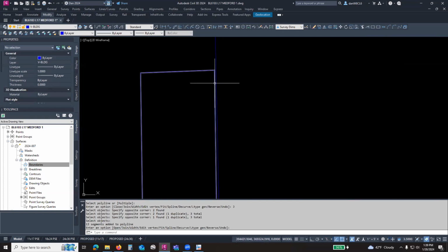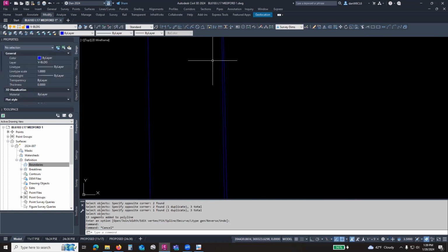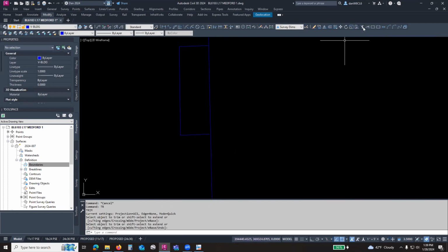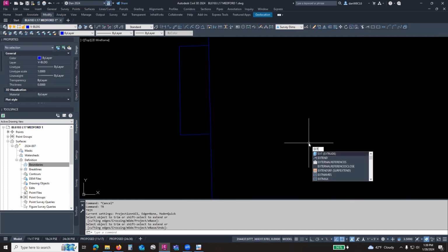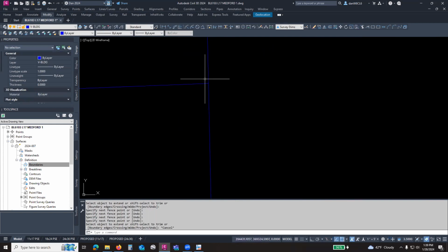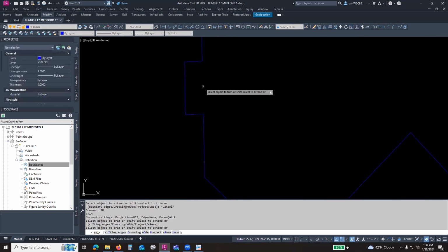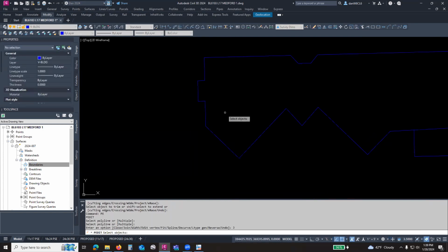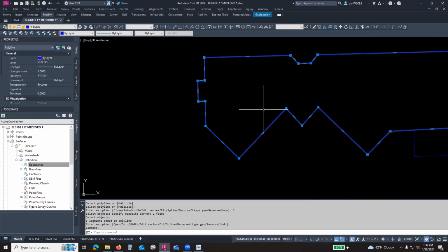What is this thing? Let's trim that. I guess the chimney. Going to extend here, or you can type extend if you don't remember. Not extrude, but extend. Draw a line across it, and look, it extended it to there. And we're going to do trim. Trim out that bit. And then I got to go polyline edit again. Join. This is all one big piece now.